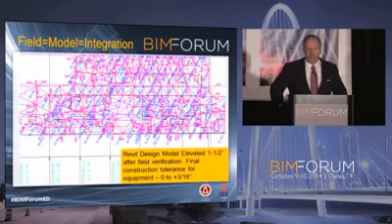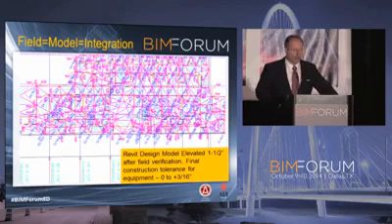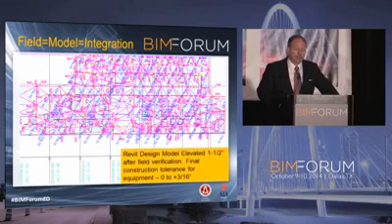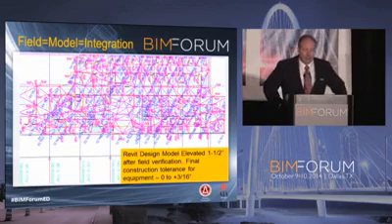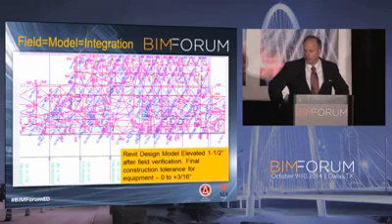Field model integration. We do a lot with laser scanning. This was an interesting story in that in this particular case, we took our total stations, had the model and the AutoCAD drawing for where the floor plate was going to go, actually laid it out, did a topo specific to exact locations, found the most efficient elevation to put the entire model at, and then raised the model at DD, which was much to the palpitation of my architect friend, but it all worked out fine.